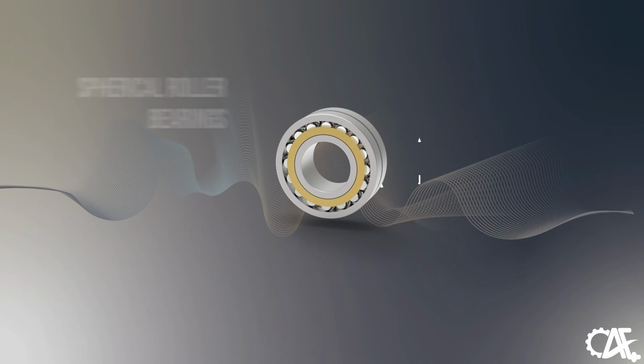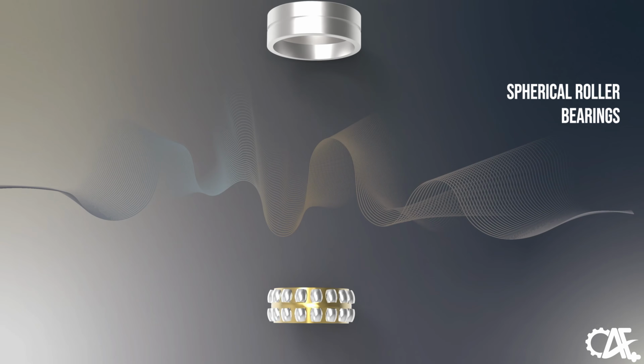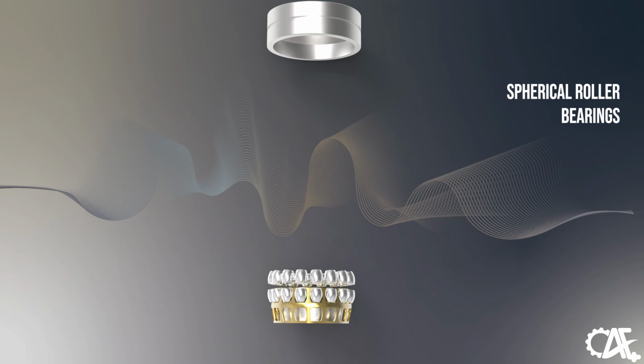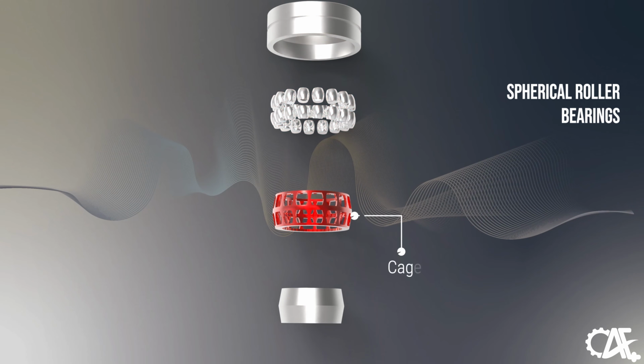Moving further down our list, we arrive at spherical roller bearings. These bearings stand out due to their ability to accommodate misalignment. They feature barrel-shaped rollers arranged in 2 rows in a spherical outer ring raceway. Such a design ensures that the barrel-shaped rollers, guided by the inclined raceways of the inner ring, can adjust or realign themselves freely along the concave outer ring raceway.